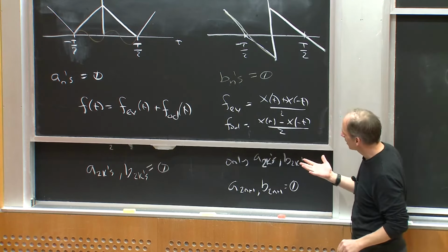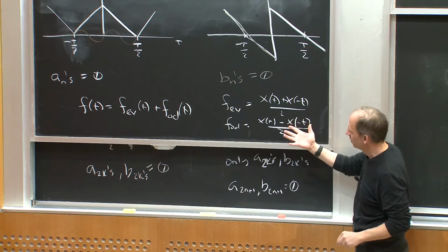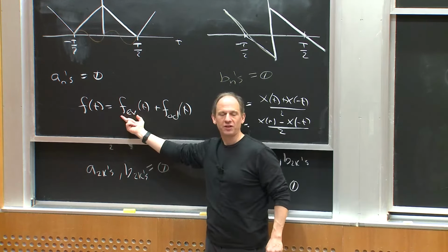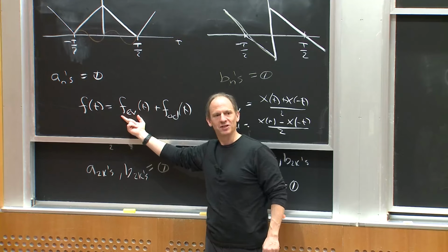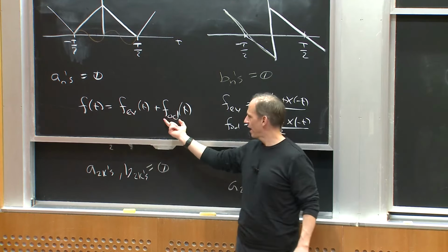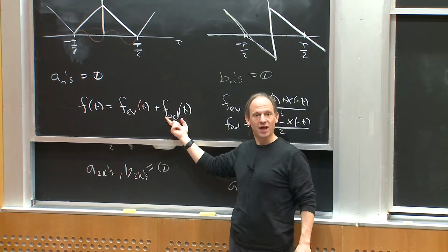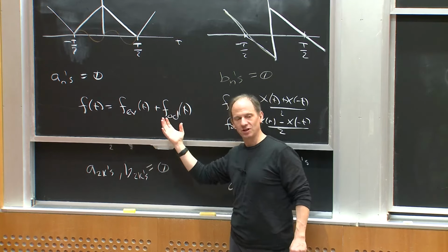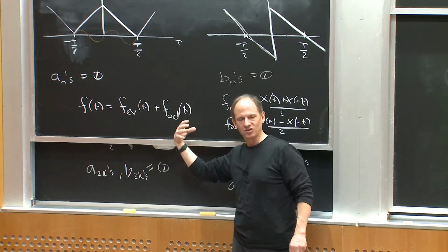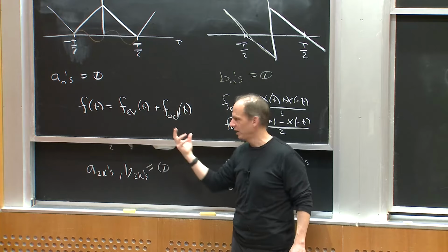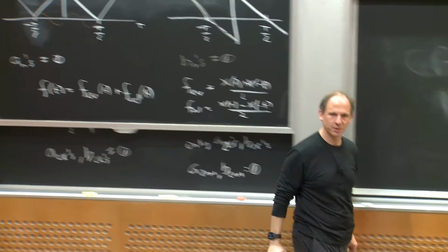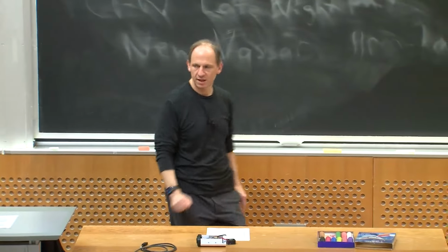So essentially, I can decompose a waveform into one term that is all the cosine components and DC, and one element that is only the sine terms, okay? So I get this decomposition, and because it's sines and cosines split, the even and odd components of the waveform happen to be orthogonal, okay?